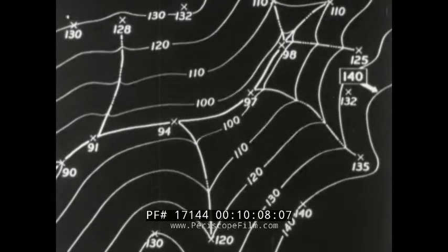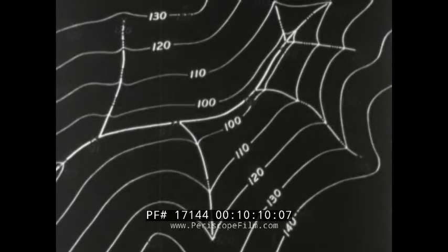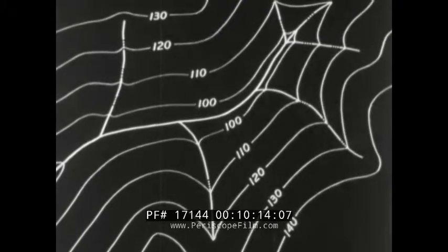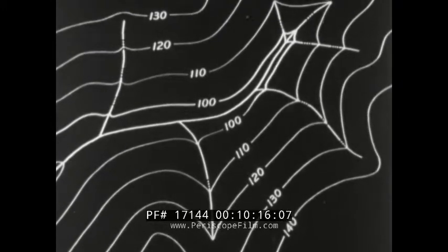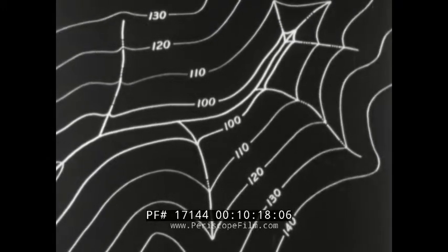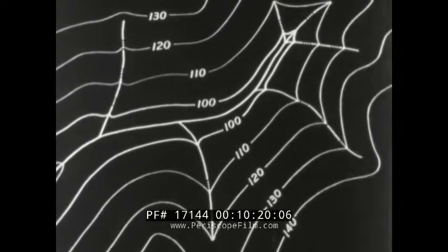The completed sketch should have all guide elevations removed and the contours numbered. Every fifth contour should be emphasized by a heavy line. In this case, only the 100-foot contour is in this category.